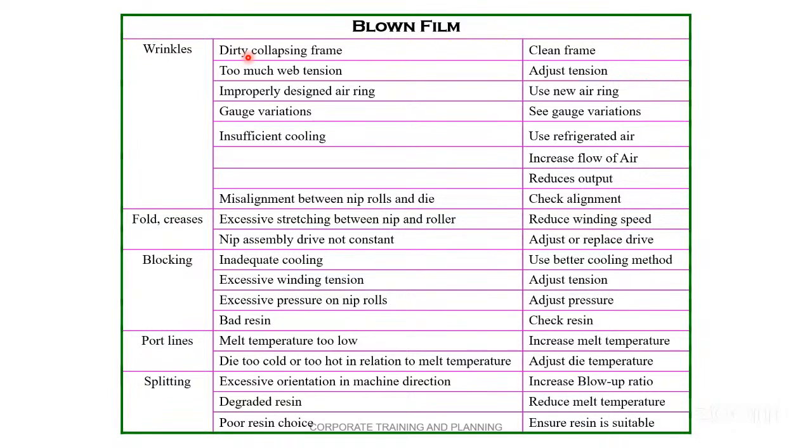Therefore, the collapsible frame also affects the outer structure. It's a wrinkle. Too much web tension, therefore adjust the tension. Improperly designed ring, use a new ring.